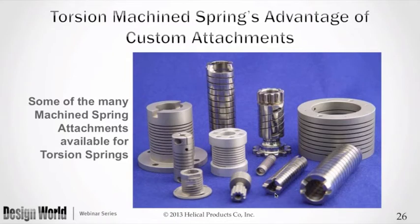But whenever we've done that, we've had to do something to resolve that force that's out there. And also we've had to worry a little bit about what happens when you bend that wire from its straight condition to a hard right angle bend, whether it be coming out the end longitudinally or going out radially. What happens to the section of the spring in that area, and do we have a stress there that's possibly not beneficial to the life of the spring? Well, with machine springs, we can put features on the ends of these springs. We can put features such as the tangs that you see there, but we can also make those tangs thick and robust. And if we only had one tang, we could make it thick and robust.